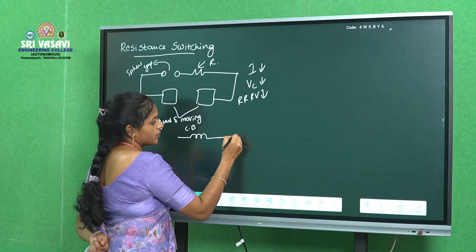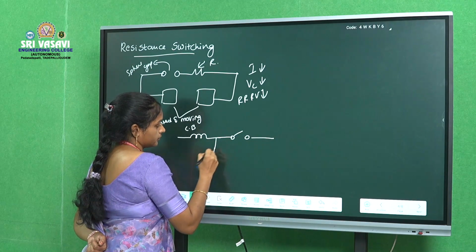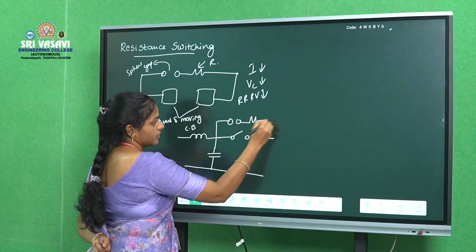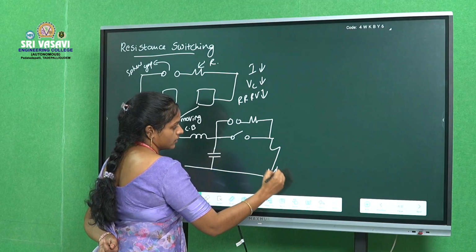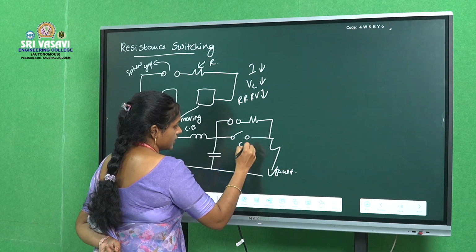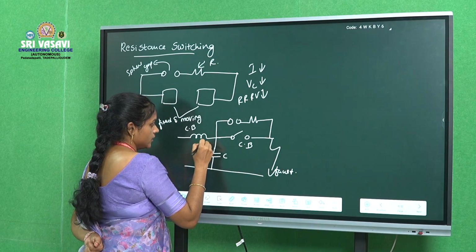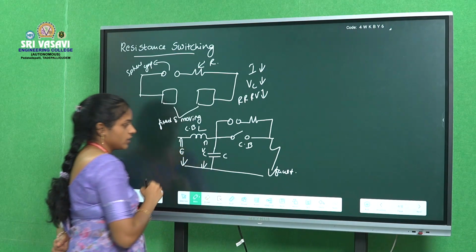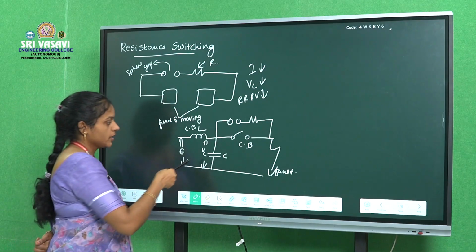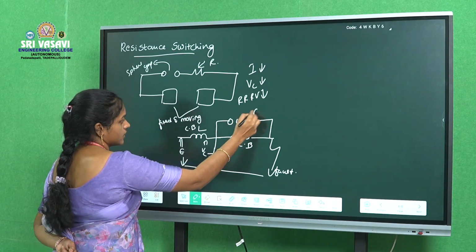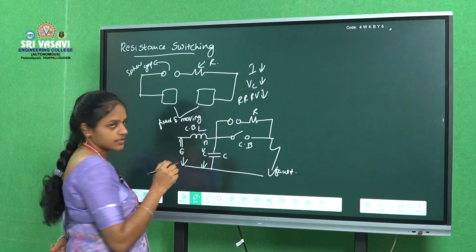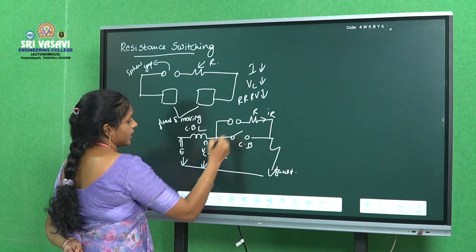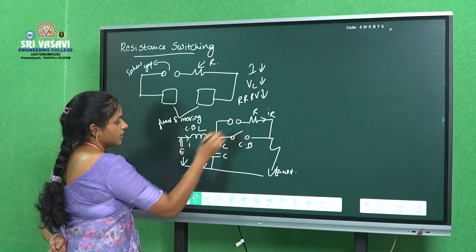This also can be solved by the equivalent circuit. So here we have the spark gap, the resistance, the fault, and the circuit breaker with capacitance C. Here Vc, here L, and this is the supply voltage E. Normally, without this resistor, the whole transient voltage appears across L and C. But here this transient current also flows through this R. Here I is split into two currents, IR and IC.